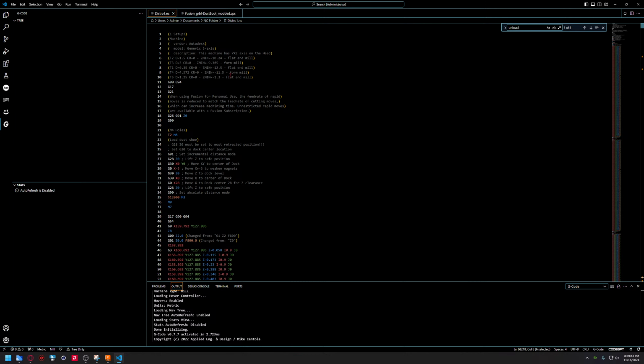Let's see the tools here. I have to check some of the tools. Tool 1, Tool 2, Tool 3, flat end mill, form mill. Form mill is the threading mill. I don't know, they call it a form mill, but this is the one it should be for drilling the holes for the M4. T3 is tapping or threading the holes. T1 is the 1/4 inch flat end mill for making the distro channels.